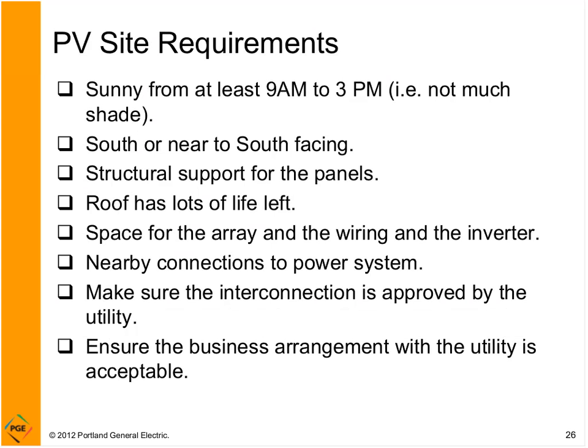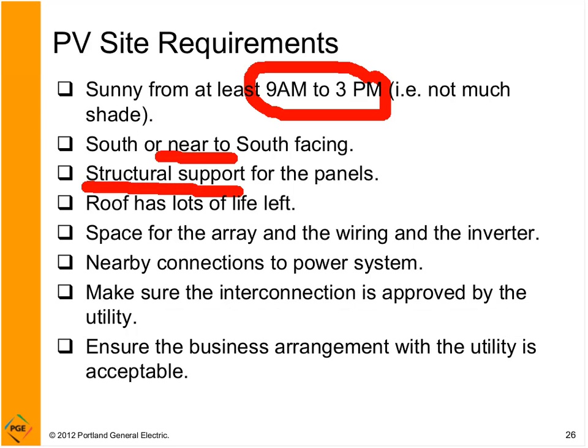Now, site requirements for PV are, as I mentioned, very similar to solar thermal. A couple things to keep in mind. You don't need to have early morning sun necessarily or late afternoon sun if you have good sun in the middle of the day. You don't need to be exactly south. You can be near south. Keep in mind that these panels need structural support, so you'll be talking to your structural engineer probably about the roof and what it can support.